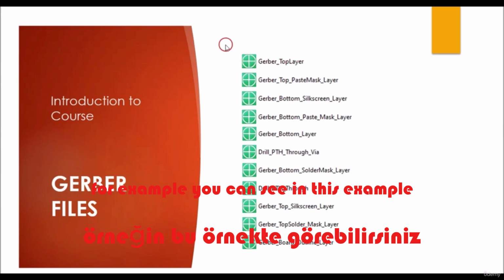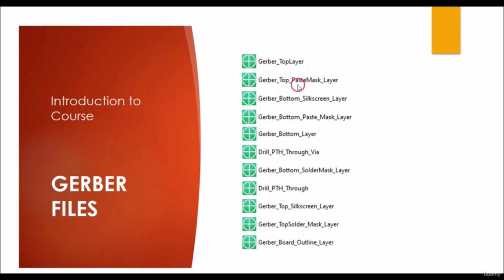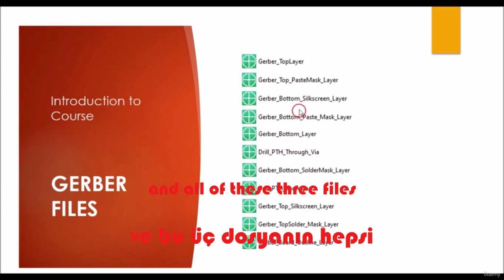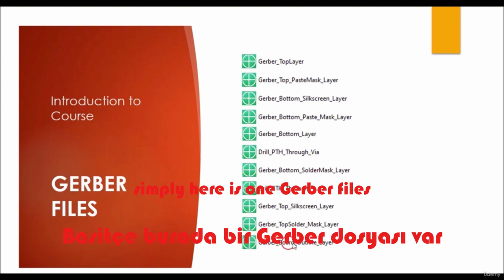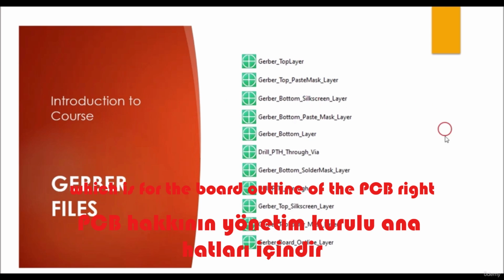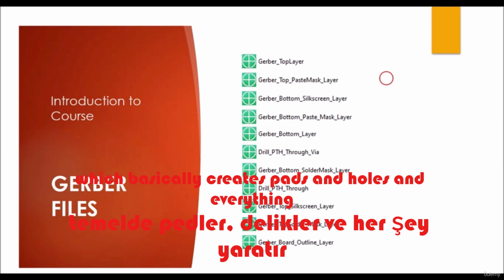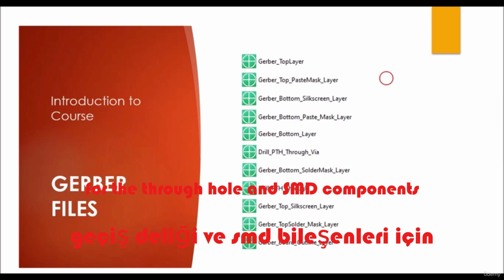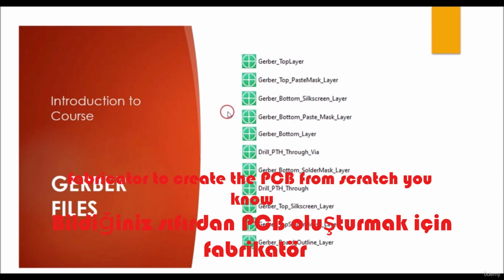For example, you can see in this example these Gerber files are for the top layer. These are also for the top layer, and all of these three files, and this one is for the bottom layer of the PCB. Simply, here is one Gerber file which is for the board outline of the PCB, right? These files are understood by the CNC machine, which basically creates pads and holes and everything for the through hole and assembly components. So these are understood by the CNC machine that is used by the fabricator to create the PCB from scratch.